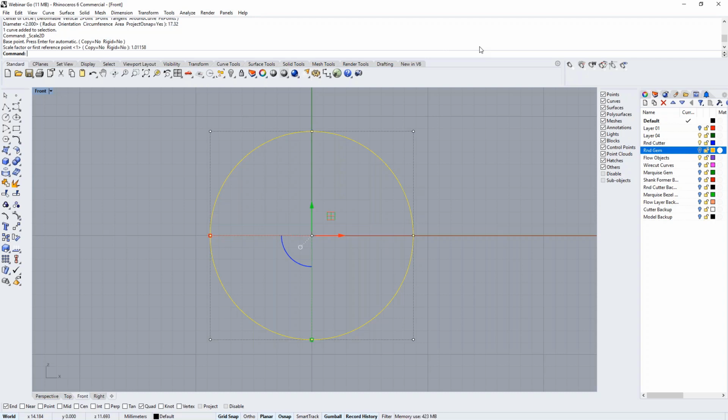But joking aside, if you're actually carving in wax, a scale factor is a little less important. You still have to scale for the casting shrinkage, but you don't have to worry so much about resin shrinkage. Also, with the piezoelectric wax printers, SolidScape is one example, the scale factor for the model itself is much less important. So hopefully that answers the question about scale factor and how I tend to approach it for my system. And again, for the third time, I think that's real specific.